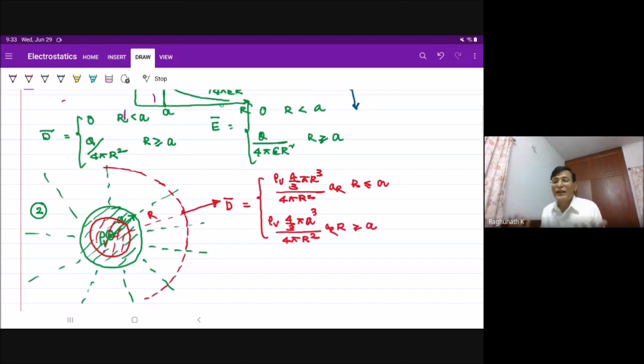Normally, whenever you charge an object, the charge comes onto the surface. Another place where unstable volume charge is there and the discussion actually happens is the Gunn diode, where a domain of charge is formed. A charge cluster is formed and it travels. While traveling, it grows, is another point for us. That is actually unstable volume charge.